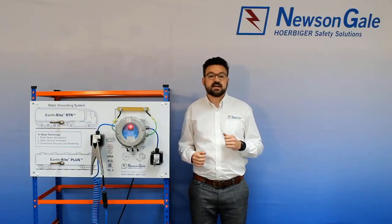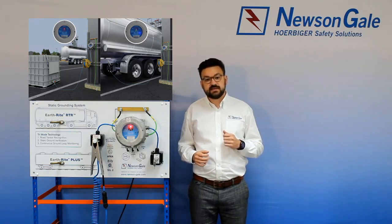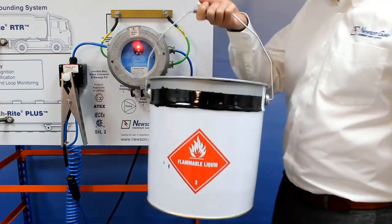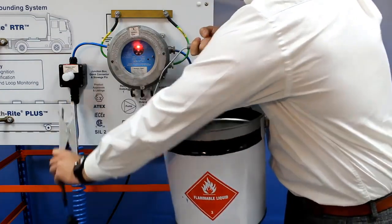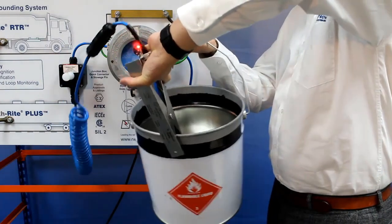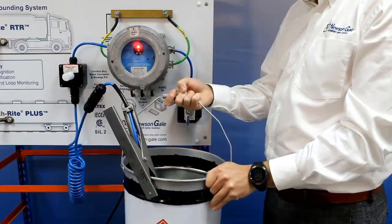Whilst alternative systems will look for an isolated metal object, the RTR looks for a capacitance footprint of that typical of a road tanker and will not work on metal vessels that do not meet this value. If we take an industrial drum and apply the clamp, as you can see indicated by the fixed red LED, the system remains in a non-permissive state. This is because the drum doesn't have the capacitance value in relation to earth typical to that of a road tanker.